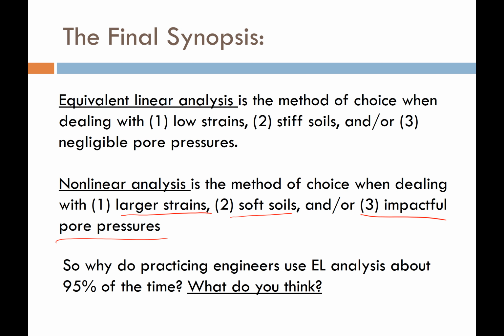Equivalent linear analysis is fast. It's been around for a long time. Generally, we don't validate it, or we don't need to validate it, because we're relying upon modulus reduction curves that have already been proven and tried in the laboratory. And because engineers don't know what in the world they're doing. And that's a dangerous combination. So the majority of engineers in practice today are going to rely upon equivalent linear site response analysis.